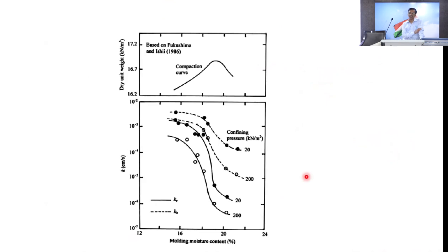Now, nowadays, is it sufficient to do a test in the laboratory with a constant head or variable head permeability apparatus? That is not sufficient, because permeability at a higher pressure is what is important. In the falling head or variable head test, I am allowing this much water to pass through a soil mass, under gravity, and seeing how much water passes through. But in the actual case, at a certain pressure I want to find out what the permeability is.